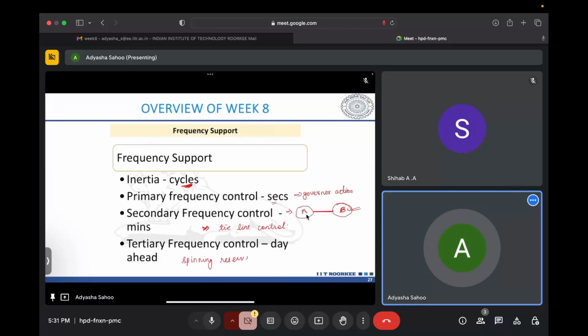To avoid the time delays, with spinning reserve the boiler will already be warm, at the required temperature, and synchronized to the system, ready to generate power whenever it receives a command from the control center by the system operator. It can readily inject or absorb power to the system. So it is procured day ahead, but applied in real time.